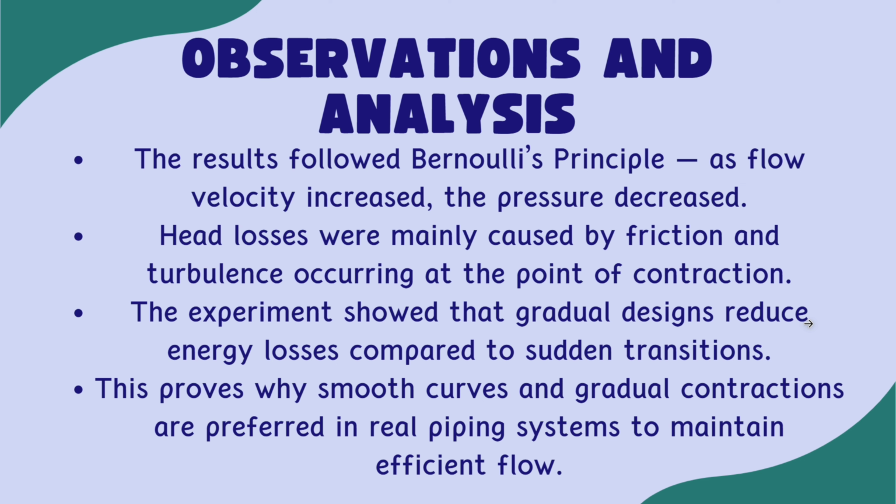Our results followed Bernoulli's principle. As velocity increased, pressure dropped. Head losses came from friction and turbulence, and gradual designs performed much better, showing why real-life piping systems are built with smoother curves and transitions to save energy.